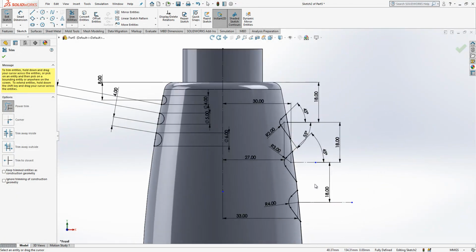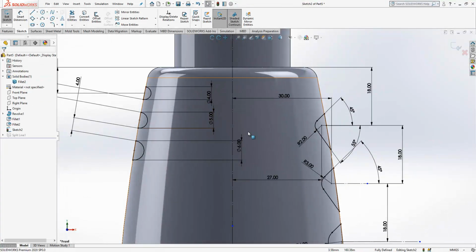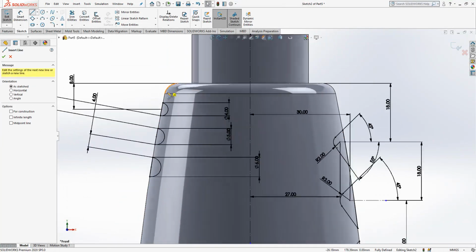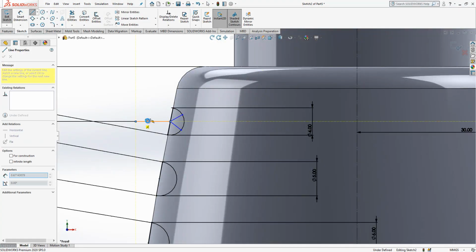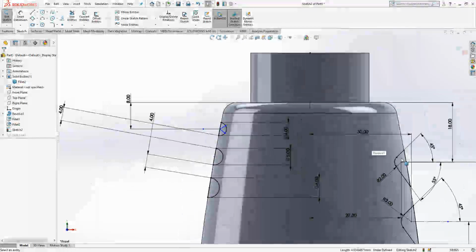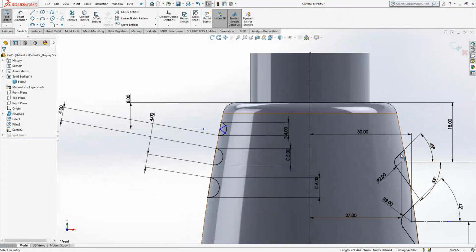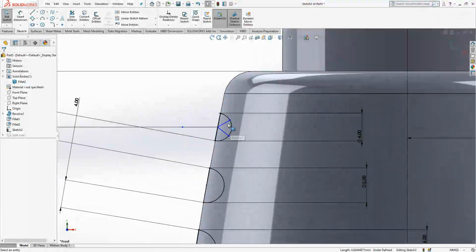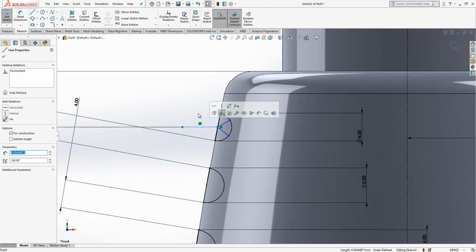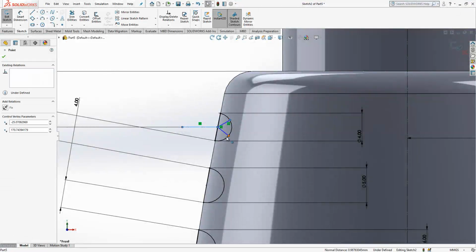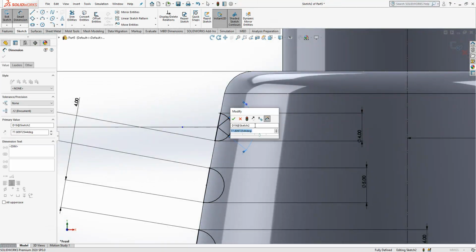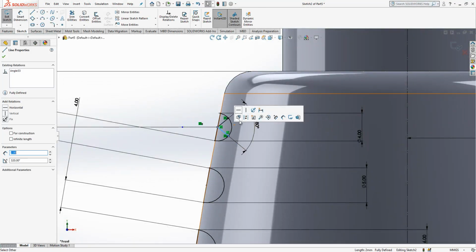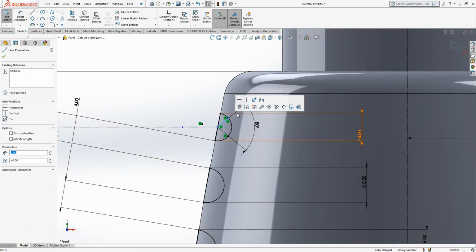So these are closed profiles. And let's make one another thing here. That's also important: define control points. Okay, we have these 2 control points. What are these control points? At the other side, we have an object with three segments. Here we have a half circle. So the program might have difficulty understanding where the control points are. To overcome that issue, let's make it like this. This is 80 degree, 80 degree, and symmetric.